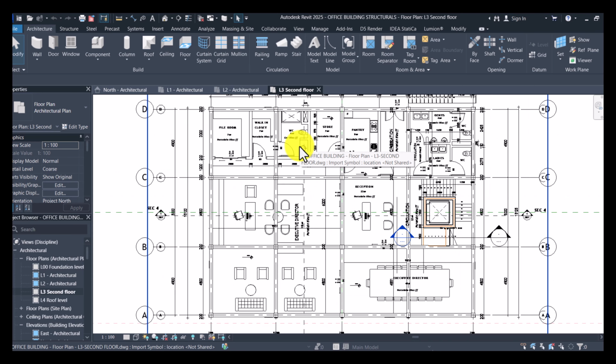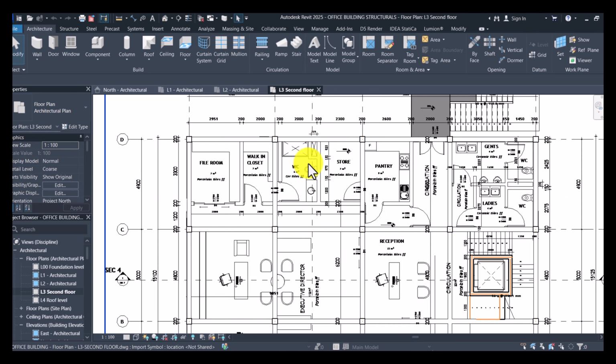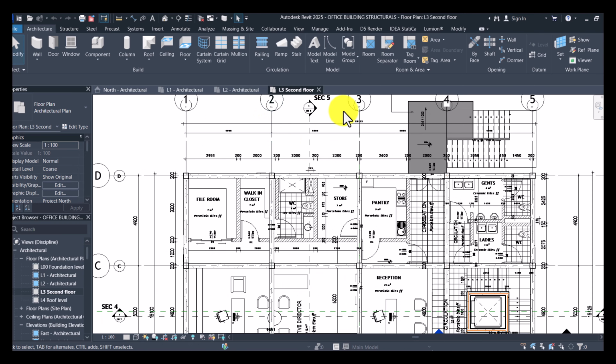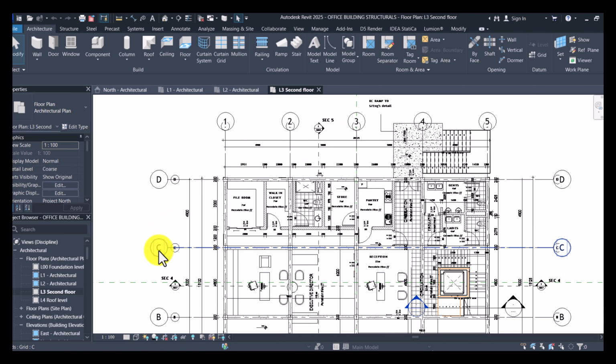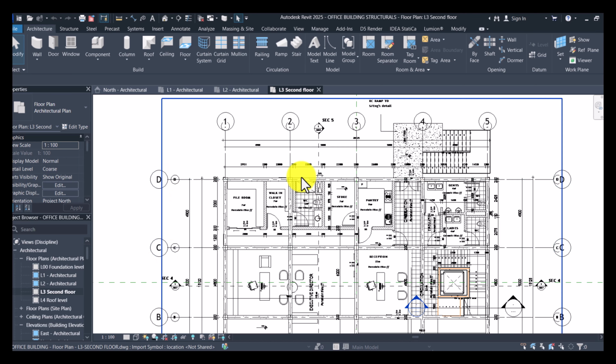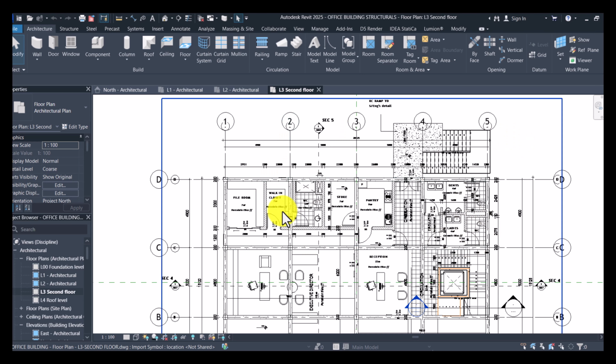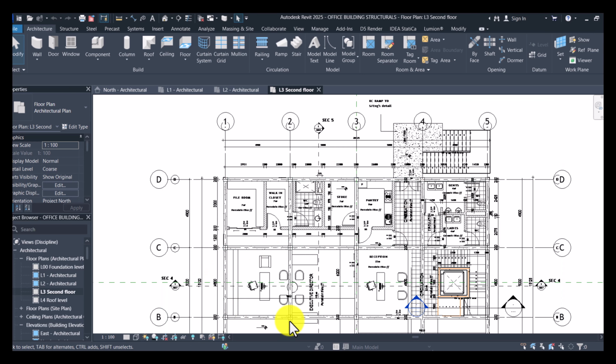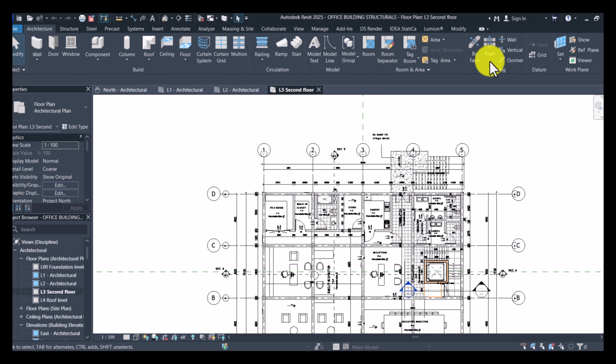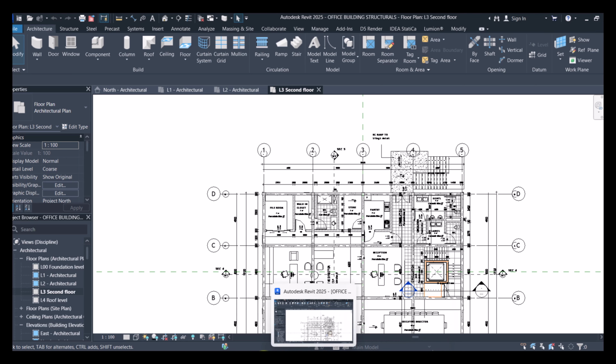Basically, same for the second floor, except this panel here between 2, 3 and this. So I have a toilet. In fact, from 2, 5. So what does it mean? Here we shall have solid floors. The rest of the panels we shall have ribbed slabs. Okay, so having understood that, let me go to Etabs.